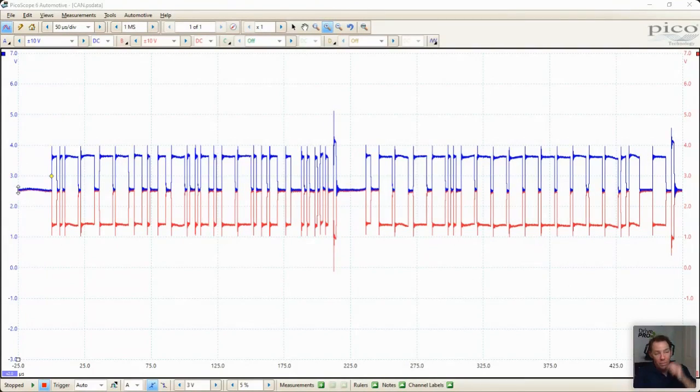Okay. So when we have a look at our CAN signals, we're looking at this now. I could click up the top here, look at my voltage, click down there, look at my voltage and do the maths in my head. Now I know with any Bosch CAN system or GM, any system that is Bosch derivative, I should have a 1 volt differential across here. Now again, that's not too bad. I can see down here, I'm about 1.5 there and I'm about 3.5 there. Well, that's actually about 2 volts across the two.